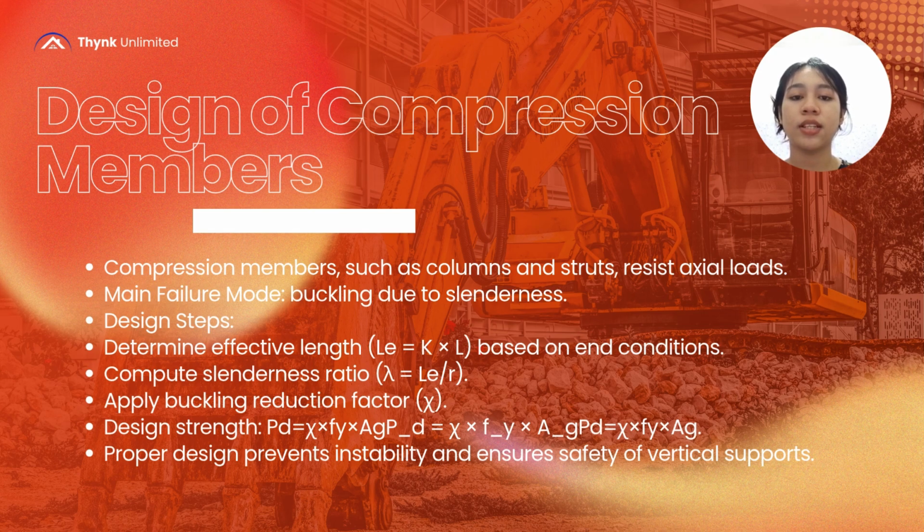Number two is compute the slenderness ratio, LE divided by r, where we divide the effective length by the radius of gyration. Number three is apply the buckling reduction factor to adjust the strength for buckling effect. Number four is find the design strength using PD = X multiplied by Fy multiplied by Ag, meaning we multiply X, the yield strength Fy, and the cross-sectional area Ag. Proper design ensures the compression member remains stable and safe under vertical load.